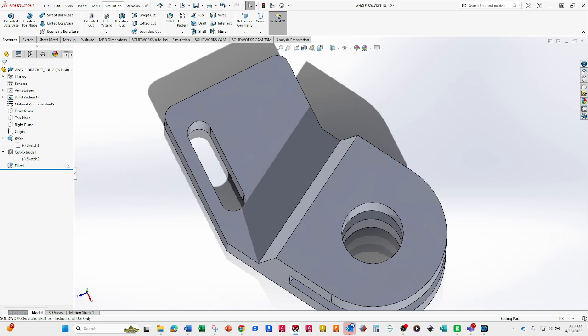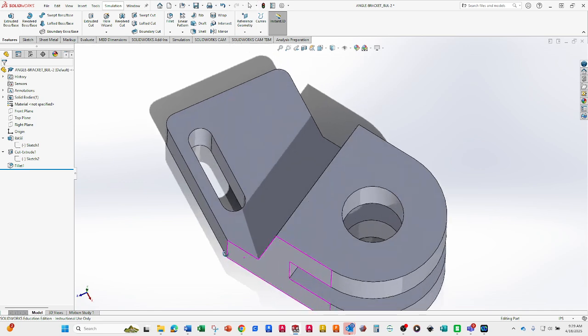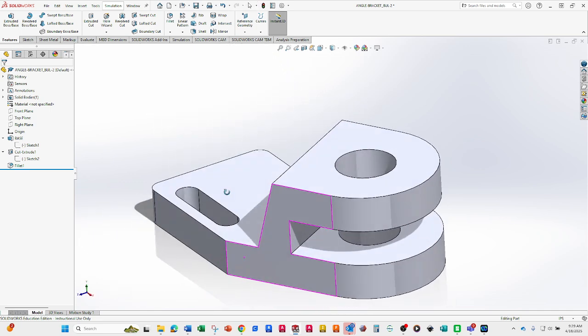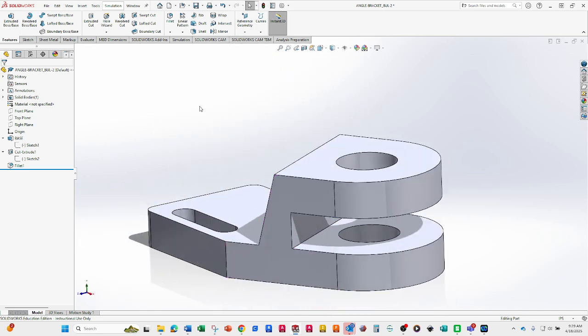But basically, I just wanted to give you a heads up, show you how this works, and no matter what modeling software you use, it's the same process. You create a sketch of the base, you extrude it up the height of the total part, which is like 2.25, I think, and then you do a cut using this here.